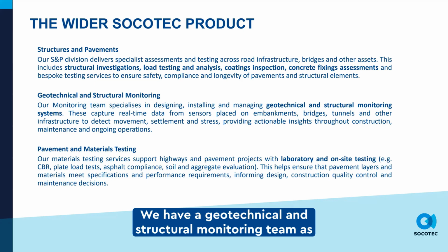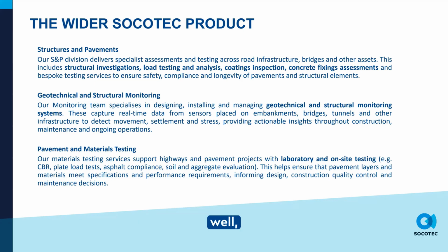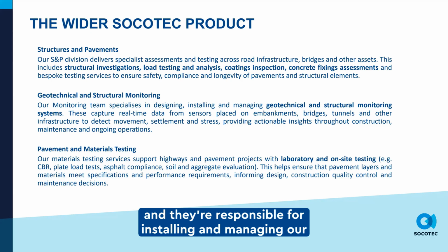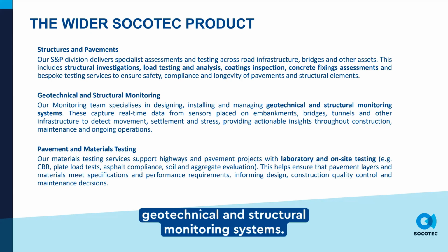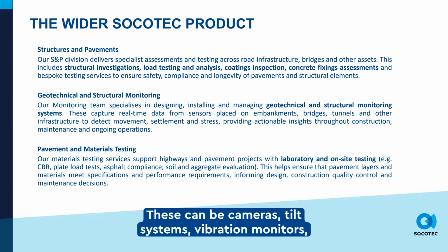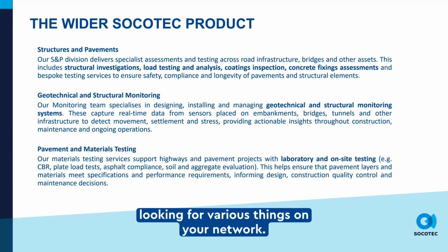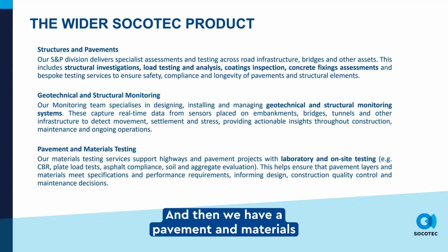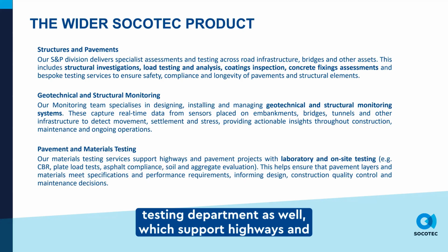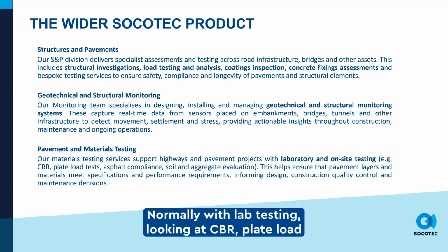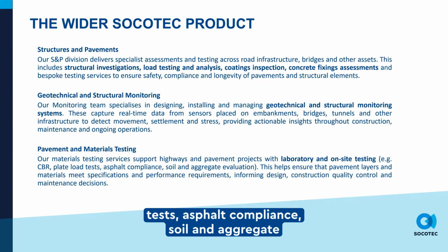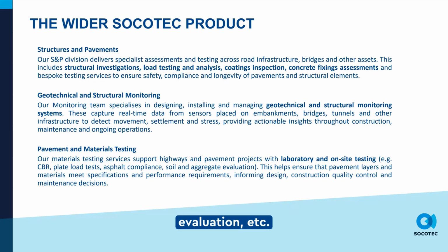We have a geotechnical and structural monitoring team as well, and they're responsible for installing and managing our geotechnical and structural monitoring systems. These can be cameras, tilt systems, vibration monitors, looking for various things on your network. And then we have a pavement and materials testing department as well, which supports highways and pavement projects, normally with lab testing, looking at CBR, plate load tests, asphalt compliance, soil and aggregate evaluation, etc.